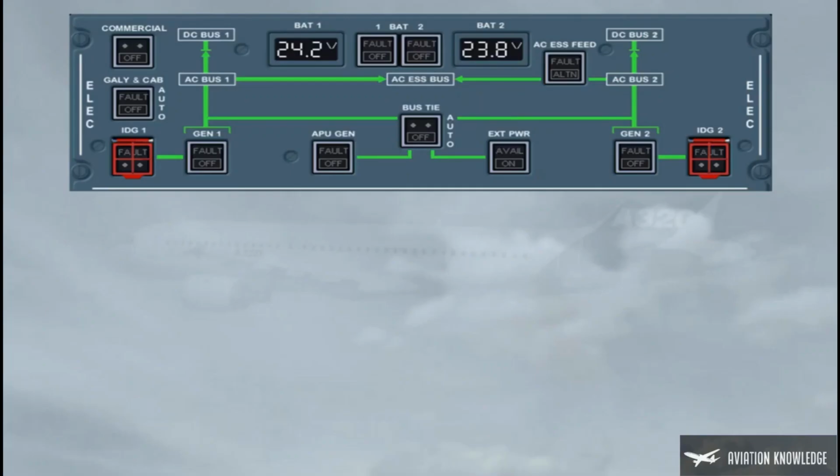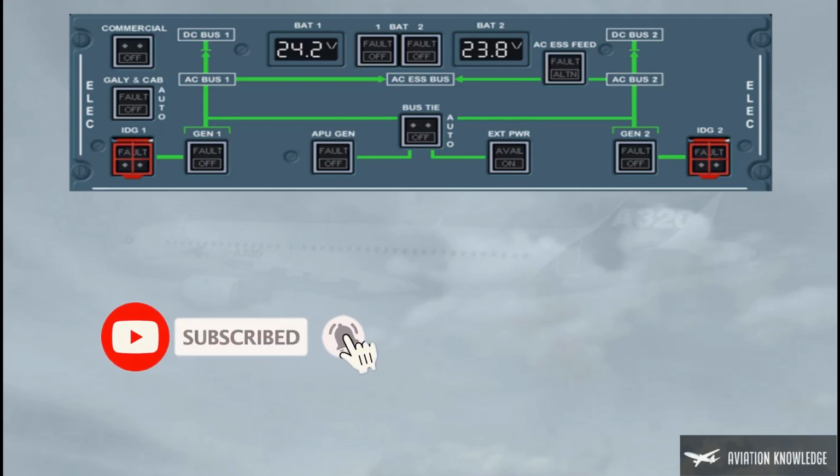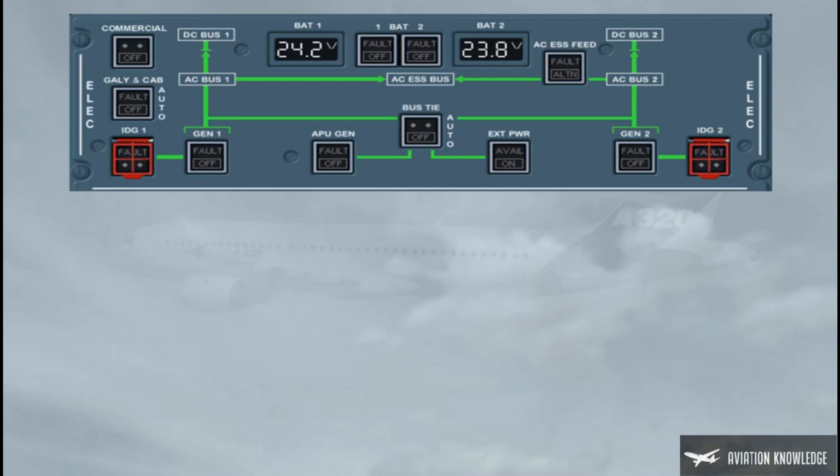After a long stop, as the aircraft has not been electrically supplied for at least 6 hours, one of the first items to check is the status of the batteries. To check the batteries, check they are off or switch them off, and check the voltages as they are always displayed. Note, as long as the DC BAT bus is not powered, off lights on the BAT1 and BAT2 push-button switches are not lighted on, even in the off position.